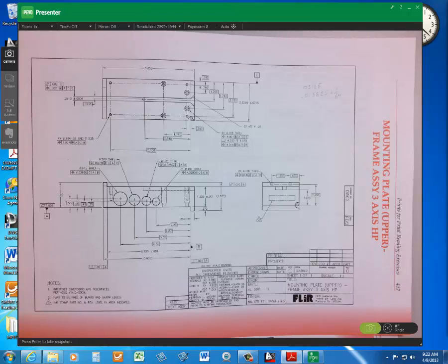All right, so why is there one for the hole and a counterbore? So that we have a separate tolerance for the hole, and we're trying to locate the hole in a greater precision. B, we have hole and counterbore, and we're doing our little math. They're both holes, and they're specified at MMC, so we do have bonus tolerance allowed.